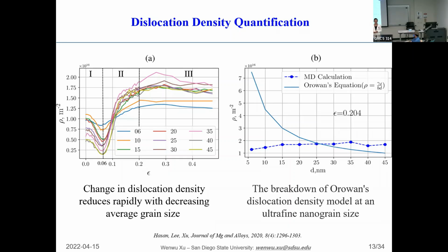So this would give us some idea once we would like to design a piece of metal according to the nanosize effect. Right. So is the strain important for plastic strain or total strain? Which one? Oh, this is the total strain. So if it is elastic, why do you get dislocation density change? This is because in the initially created structure, there are some partial dislocations situated at the grain boundary region. Very good. Thank you very much. That's a good question.